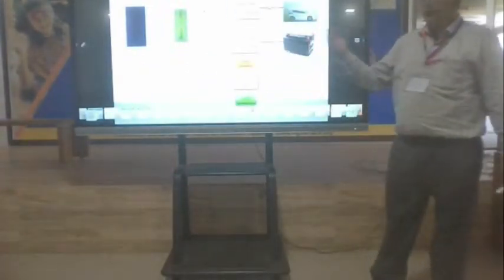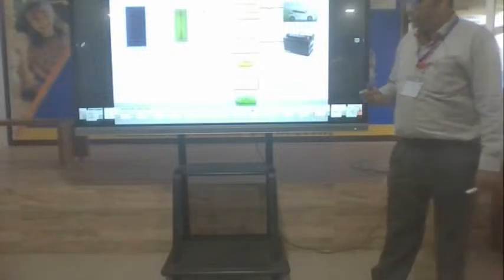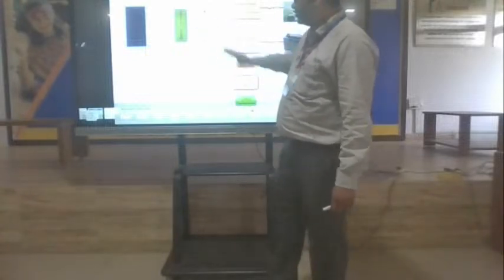Now we can see how algorithms like the Grey Wolf optimization algorithm, Whale optimization algorithm, and PSO, particle swarm optimization algorithm, all the latest swarm intelligence based soft computing techniques, you can use for the controller design. Here you have the PV panel installed capacity. The MPPT algorithm will be used for extracting maximum power from the PV panel, which will generate the PWM pulses and give them to the converters.